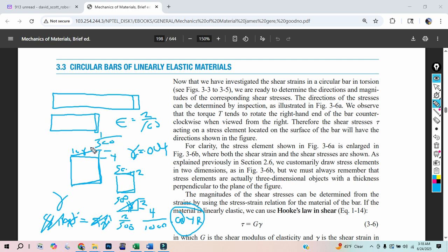Okay, let's get the denominator to be 1,000. This becomes 2, and we get 0.002. The length was 1,000. We can lengthen it by 2, and that's 0.002. So I can have any length, whether it's short or hella huge, and I just know that I can strain it in the axial direction by this 0.002.